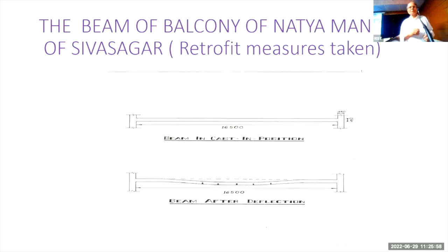Here, I want to emphasize on what basis I have told the design is wrong. The first basis, by seeing the design, there is a code provision, which is the consideration of the deflection. We design a beam for 2 things. One, limit state of collapse in flexure, and other one is limit state of serviceability. So I got the comment straight away on the basis of the limit state of serviceability. I didn't look into the other aspect. By seeing the design, I knew that the limit state of serviceability is not satisfied.